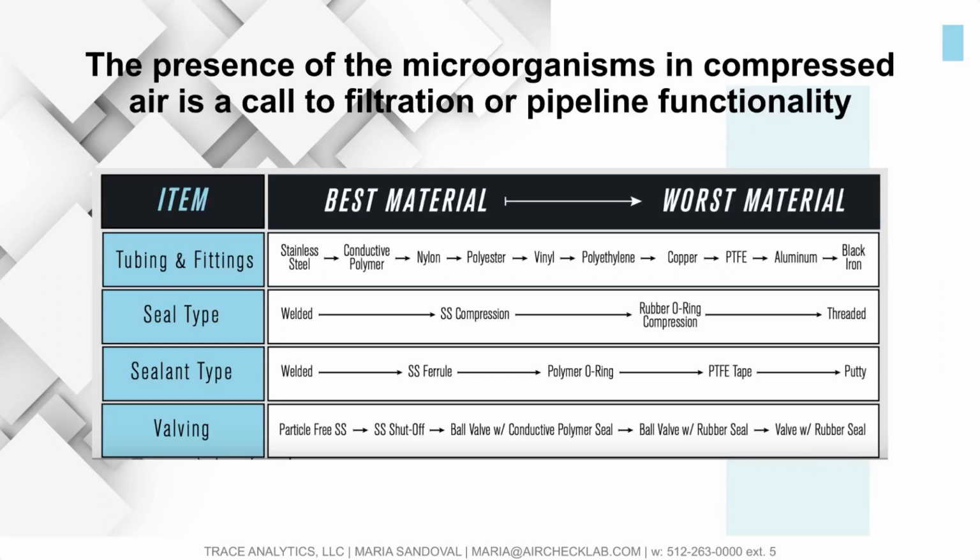There is no risk of degradation there, because you will get degradation if you use putty or if you use PTFE tape. And same for the valves. You want to make sure that you're not using rubber seals for food grade compressor usages, or ball valves with rubber seals. You want to be using stainless steel shutoffs.